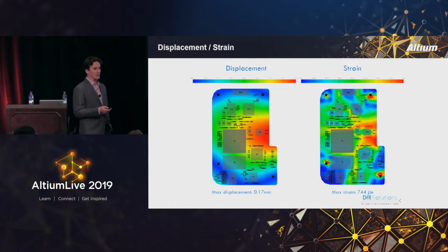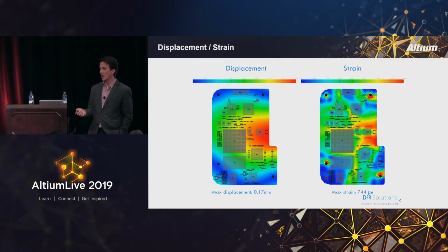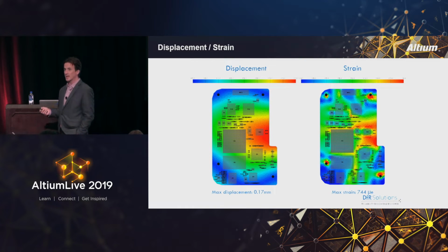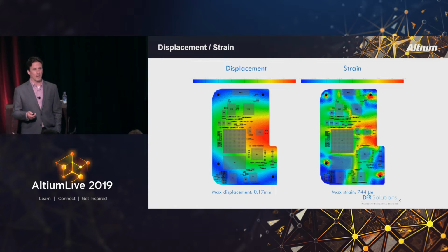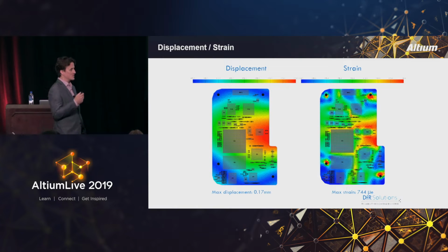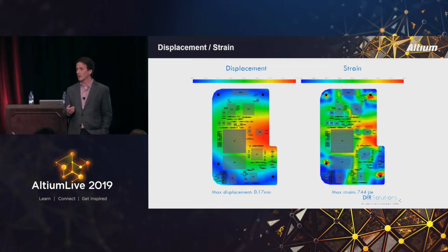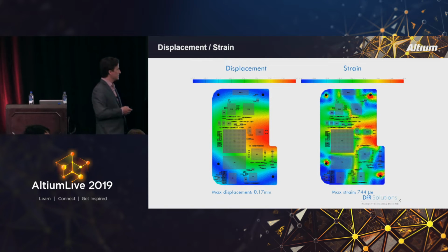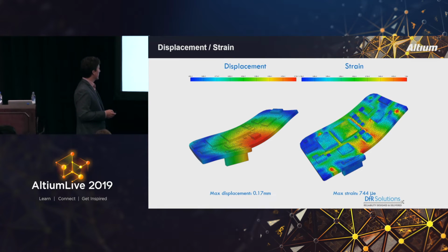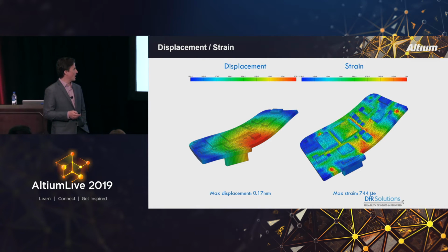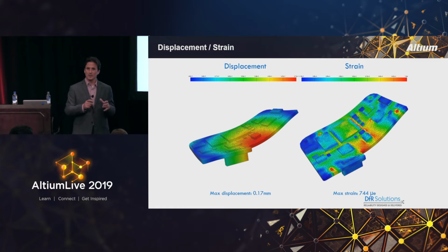The other thing that is available to us, and one of the weak points of any design in my experience has been BGAs. For BGAs, what's available to you is edge staking or underfill. But you can see how much that board twists under a drop event.